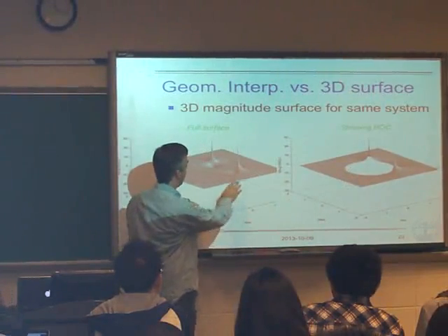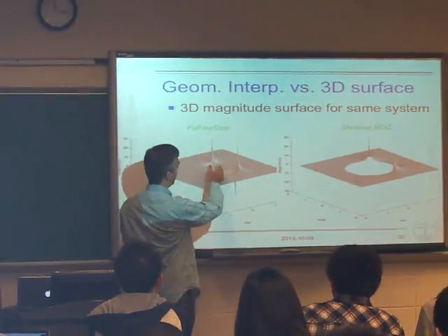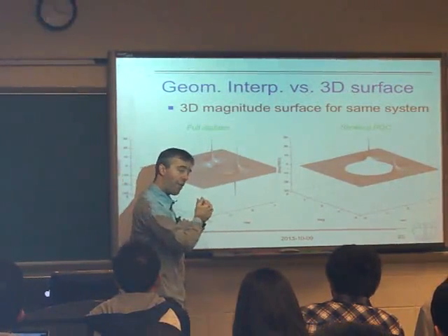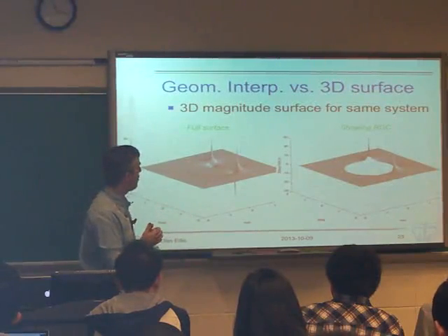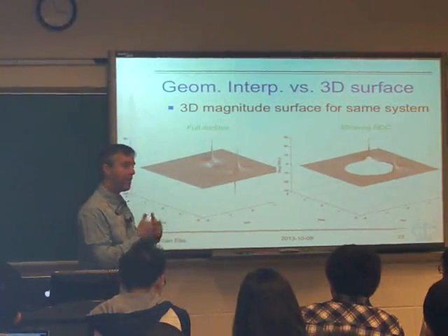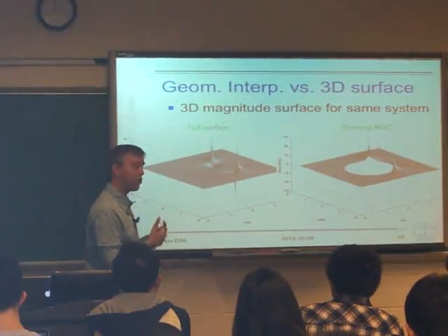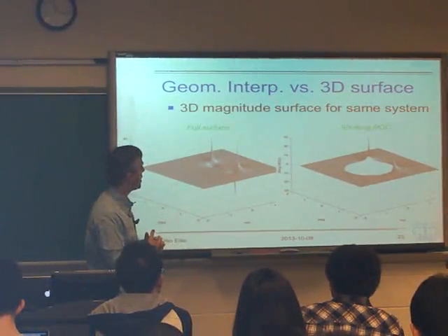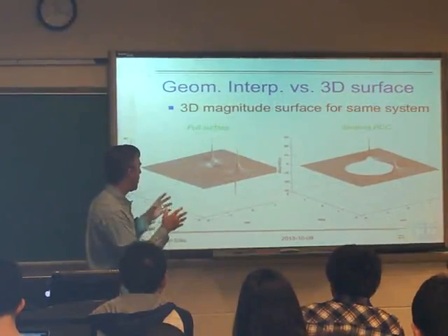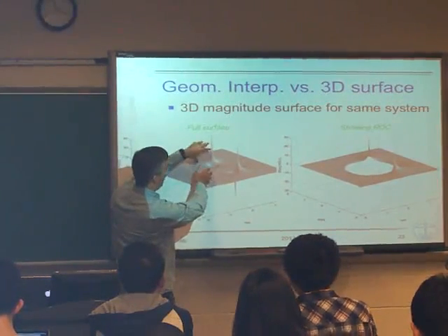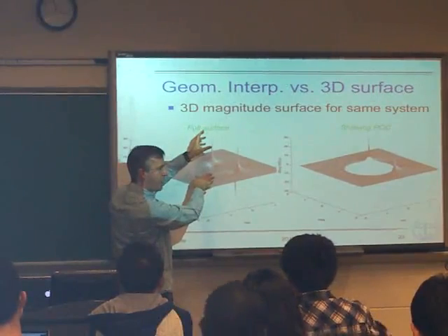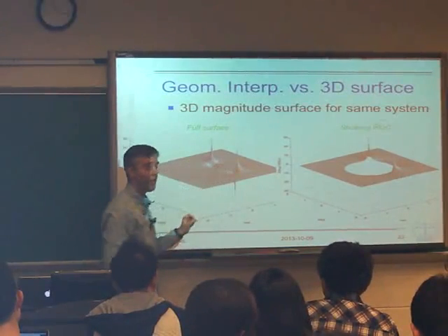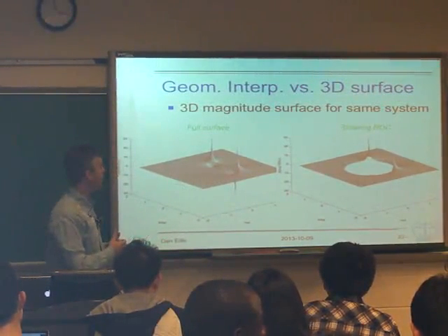And in fact, we could imagine moving these poles and zeros around to get higher bumps, or broader or narrower bumps. And now we're beginning to see why the Z transform is this very nice domain for thinking about how to control the properties of the systems we're building, how to control the frequency domain properties of these systems. That's the real point. These bumps are very intuitive to think about, and moving them around is a natural thing to do. And then how that influences the behavior on the unit circle, the Fourier transform, emerges naturally out of that.